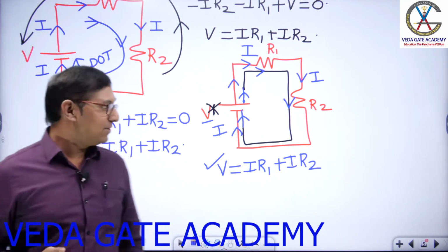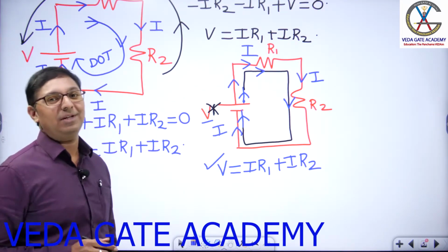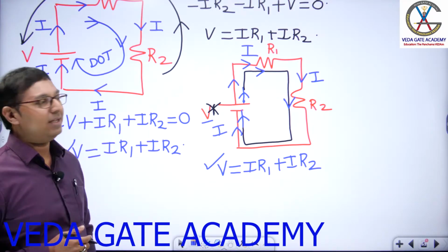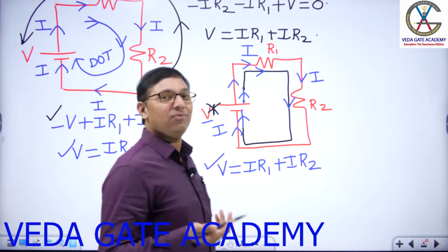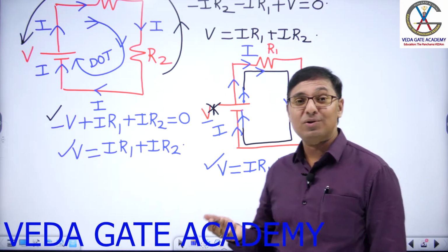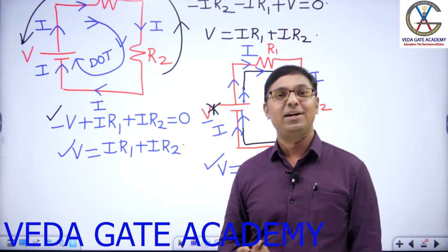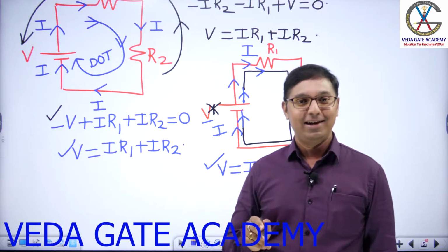So, please observe here: many will feel a voltage rise as a voltage drop, which is not true. I'm not using that class, but it appears like this. If the circuit is complex, you can't find where the voltage rise and where the voltage drop is. Why? Because in some scenarios, sources do absorb power to satisfy KVL.